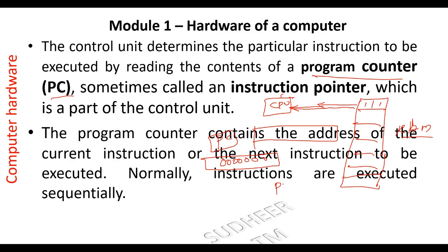While each instruction is being received into the processor, the program counter will automatically increment, automatically adjusting its content to the address of the next instruction. After executing the present instruction, once it is completed or just before its completion, the program counter content will adjust itself to the memory address of the next instruction. Then the process will repeat. The control unit will throw the program counter content to the address bus.